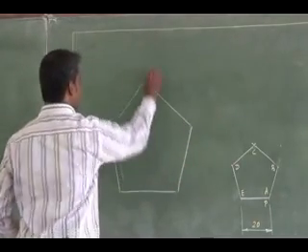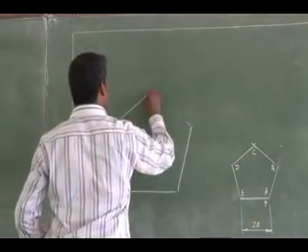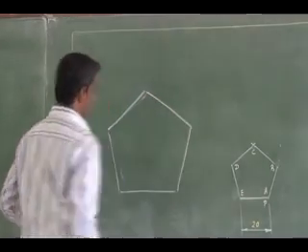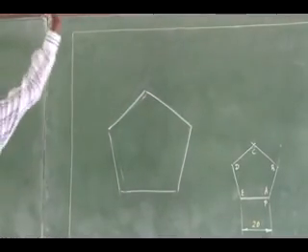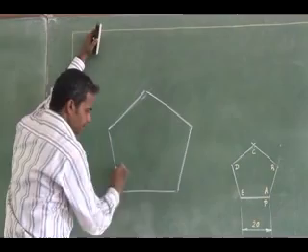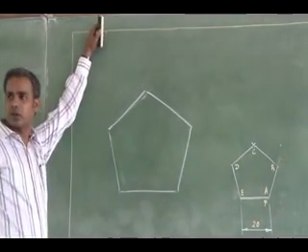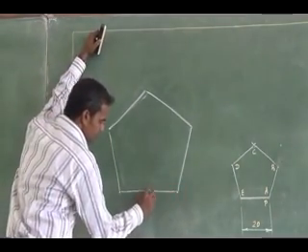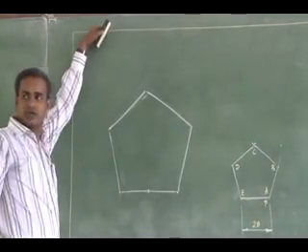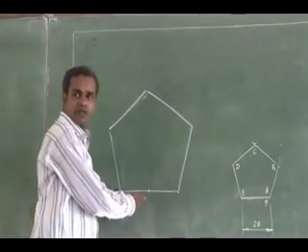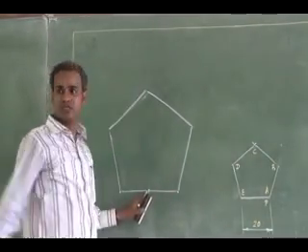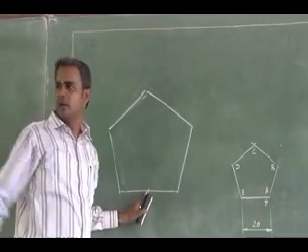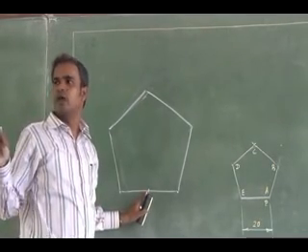How we can get the pentagon is, center for the pentagon is, I have a pentagon like this. So if you take any two sides, draw perpendicular bisectors. You mark the middle of any two sides, you join that to the opposite corner. This is a construction, our intention is to mark the center. The construction should not be visible.